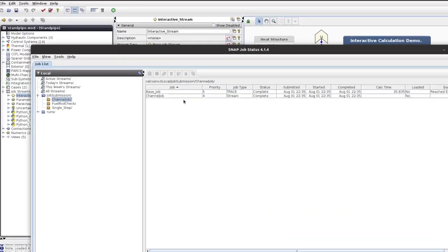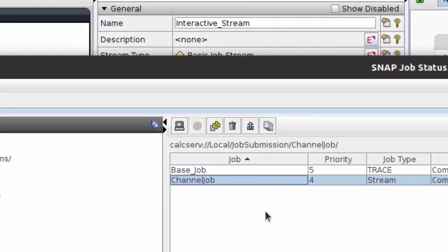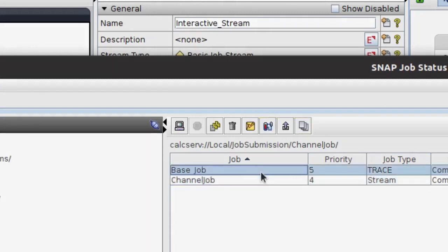This task table is accompanied by a toolbar that allows the user to perform various operations like opening the job console, releasing the job from the calculation server, deleting or importing a job, and viewing the available output files related to a submission. Each job is separated into individual tasks that are populated within the task table. The toolbar contains several options that are common to all tasks, but also includes options that only appear when appropriate.